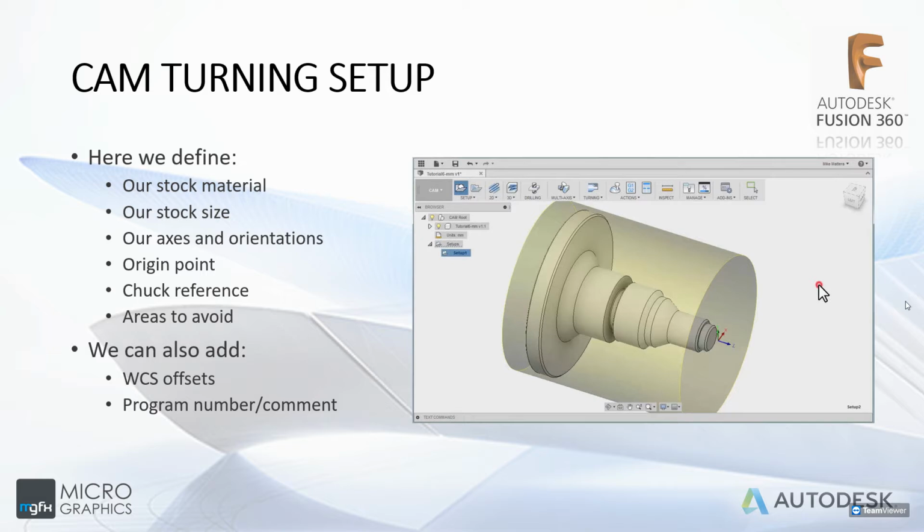Of course, the CNC machine doesn't know anything about the starting stock. So you've got to tell it, okay, which way is the Z direction, which way is the X, which way is the Y. You've got to tell it where on the model is 0, 0, 0, meaning your origin point. Again, you'll have all these options to flip them, change them around.